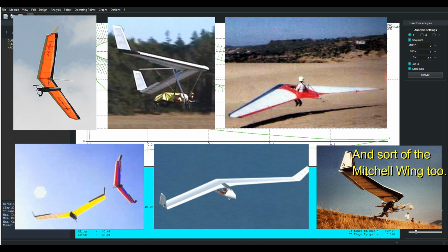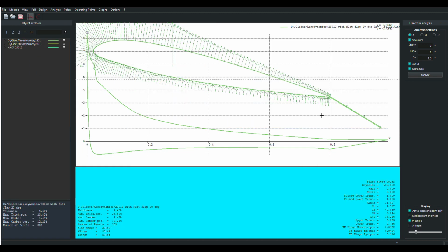And I suspect that despite all the PhDs at Stanford, it wasn't something that they thought through. They picked an airfoil that was appropriate for their type of flying, and then they just cut out the size elevons that they needed for control effectiveness without giving thought to this phenomenon, because this phenomenon only occurs in a very narrow region of Reynolds numbers and speeds, and it's quite easy to accidentally sidestep it and not know a thing about it.